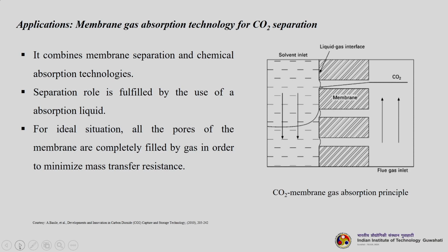Another application is membrane gas absorption technology for carbon dioxide separation. It combines membrane separation and chemical absorption technologies. The separation role is fulfilled by the use of an absorption liquid. For an ideal situation, all the pores of the membrane are completely filled by gas in order to minimize mass transfer resistance. So, this is the carbon dioxide membrane gas absorption principle.